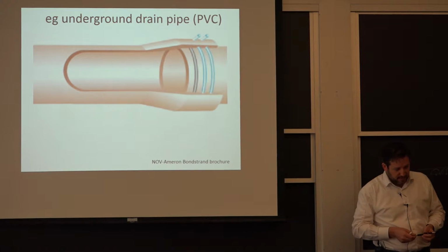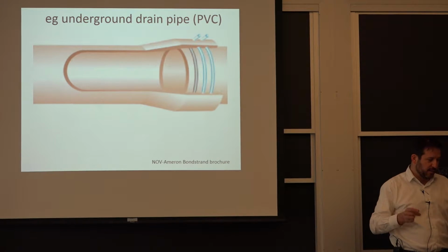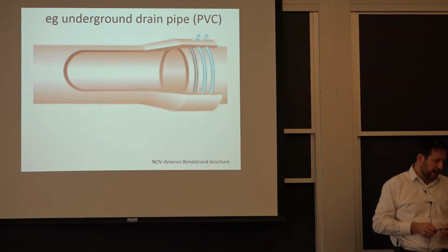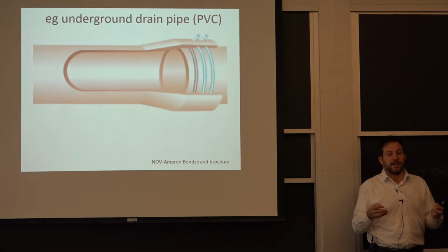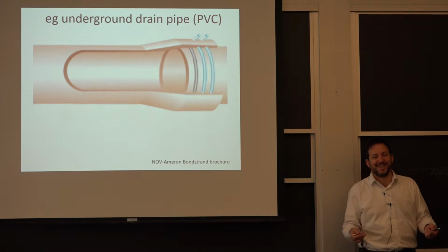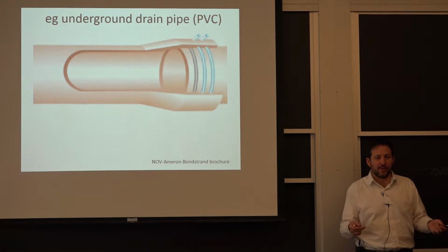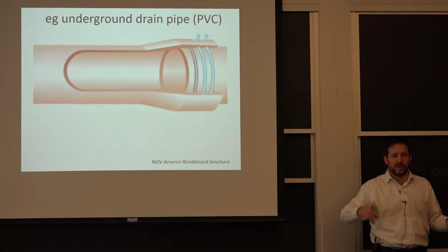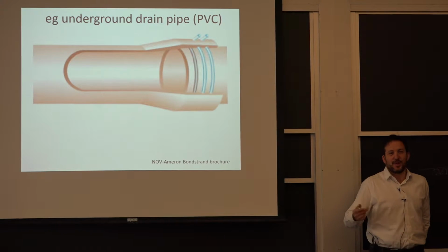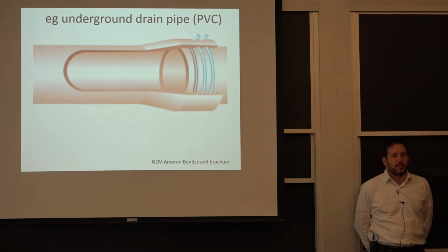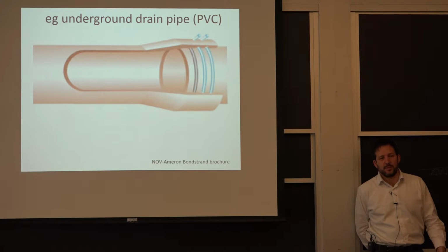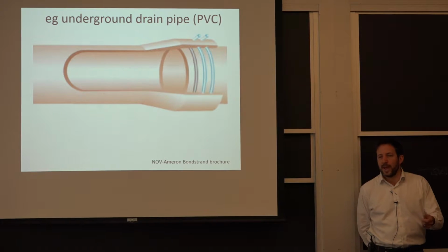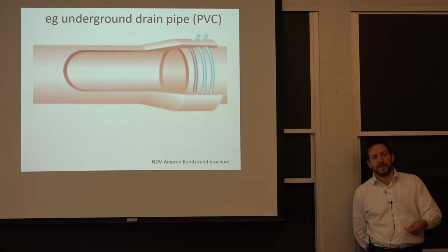So the question was about the difference for house plumbing, more or less, in terms of noise. It's twofold. A lot of the noise in a home is going to be because people didn't put all the hangers on. If you have a copper plumbing system that has the hangers, by the code, every so often, there won't be noise, really. If we're thinking as far as the flow itself, yes, a plastic will damp a little bit more the flow of the liquid through the line.